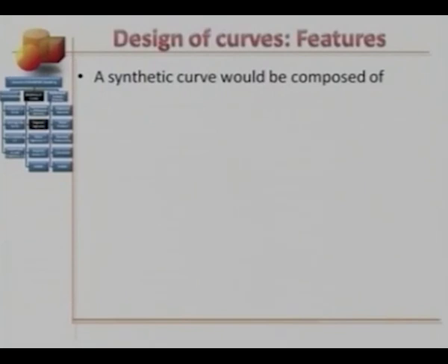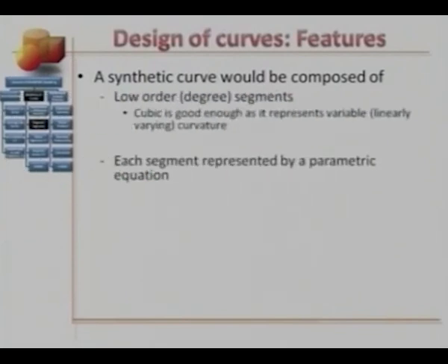Hello, this is lecture number 14 on the design of Ferguson segments and curves. Design of curves, features. A synthetic curve would be composed of lower order or lower degree segments. Here, a cubic segment will be good enough as it would represent variable or linearly varying curvature.